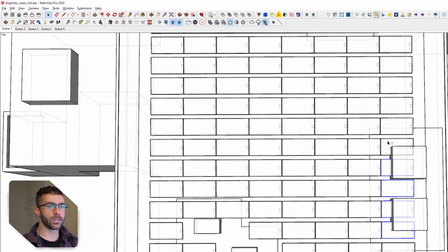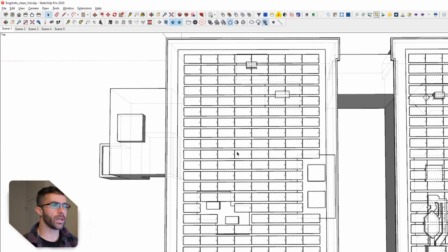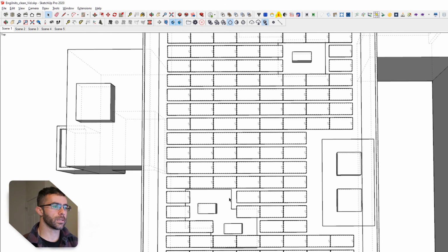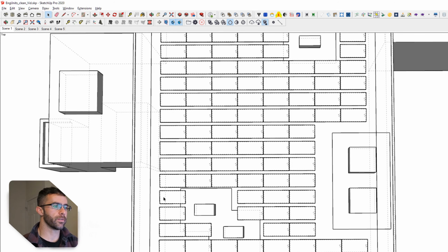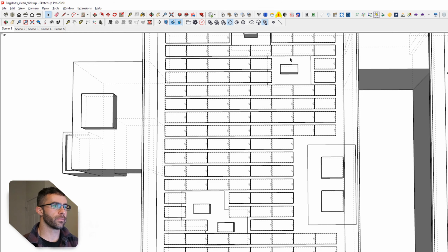These modules need to go. So then I just go through and I start deleting modules that interfere. Those interfere. Those interfere. These look like they're interfering because of the offset issue, so those would have to go. Those need to go. This is telling me I probably want to shift the whole array 2 feet left.